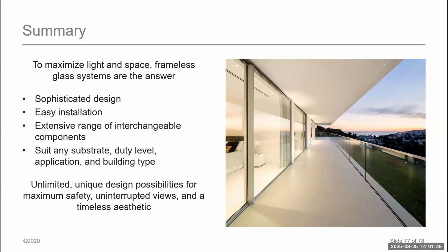We start talking about a post and rail system. We have a flange, we have a post, we have 4 anchors at every post. We have glass clamps, we have a saddle, we have a top rail. We have much more components. Our precision must be much greater when we are ordering our glass because they got to fall right into those glass clamps, where our precision can be a little bit less when using a base shoe. So those are things to take in consideration.